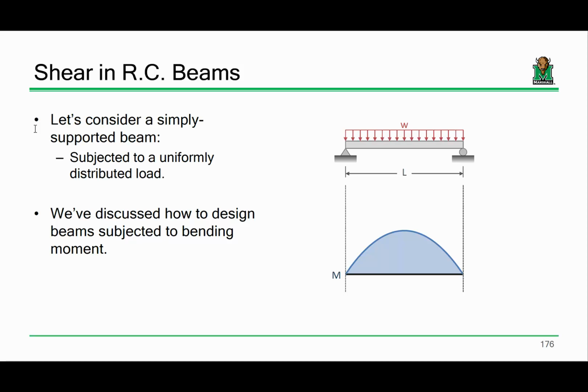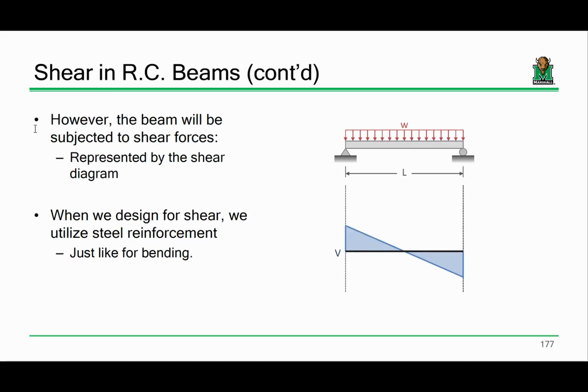For any other scenario, you of course have options. You can just break out pencil and paper and do some structural analysis. You can use one of the design aids. You could run it in RISA or something like that. So there's a plethora of different ways to do that, but that's looking at moment. Don't forget there's also shear going on as well.